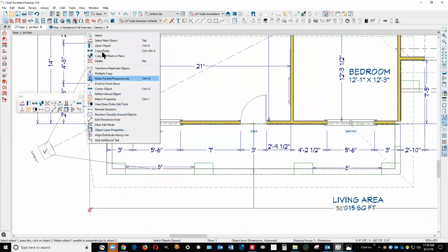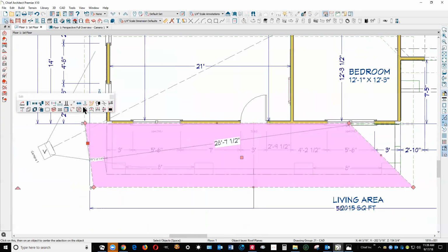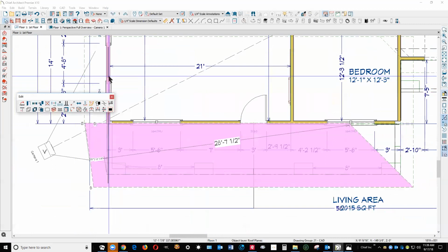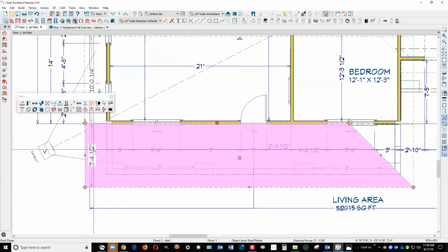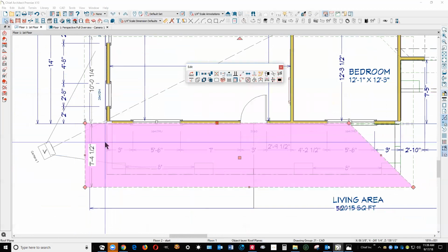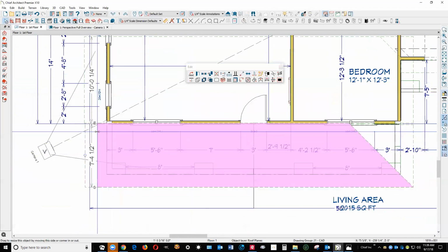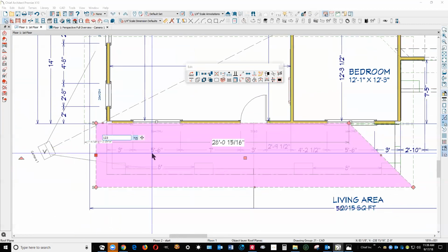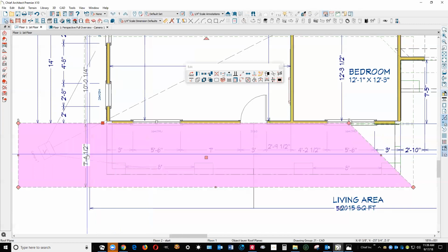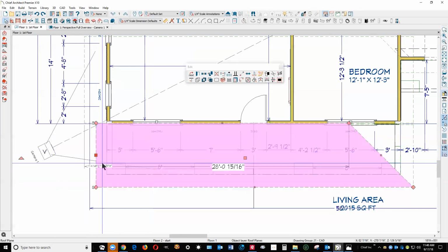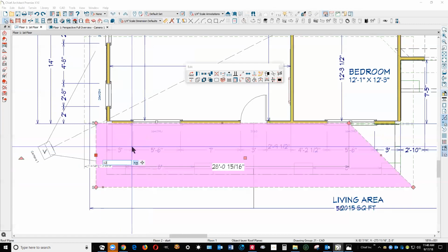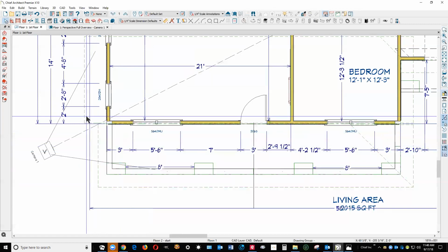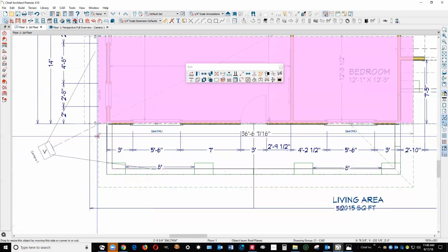Well, all right. I'm going to take this and straighten it up. There it is. Parallel perpendicular tool. Line that up with the other roof plane. Gets the overhangs. I'm just going to set it to 12 inches. Not 123, but I wanted to set it to 12. There we go. We'll set this one to the same overhang.